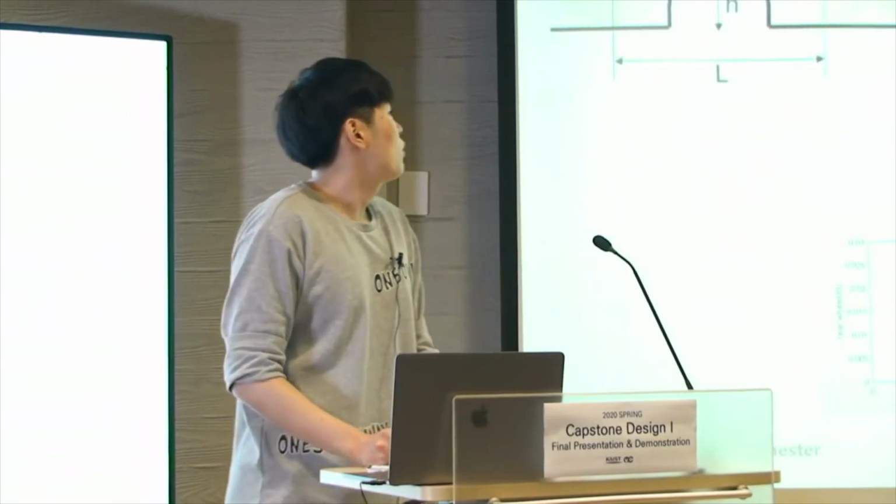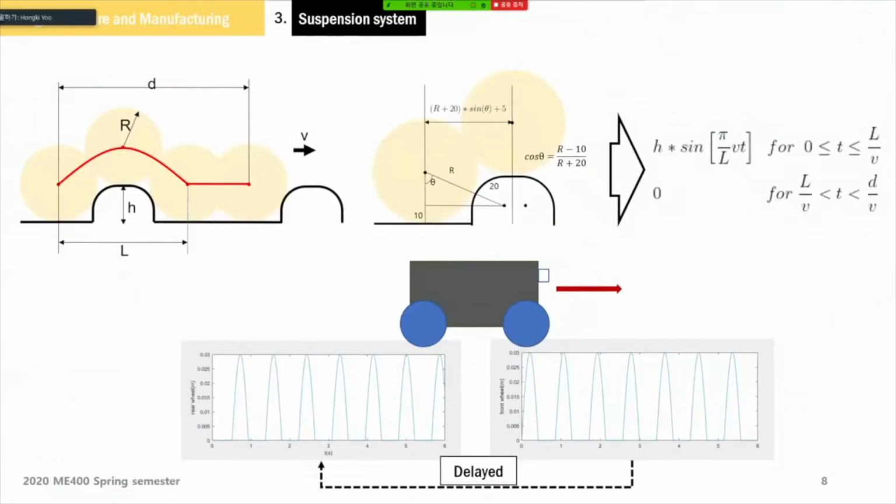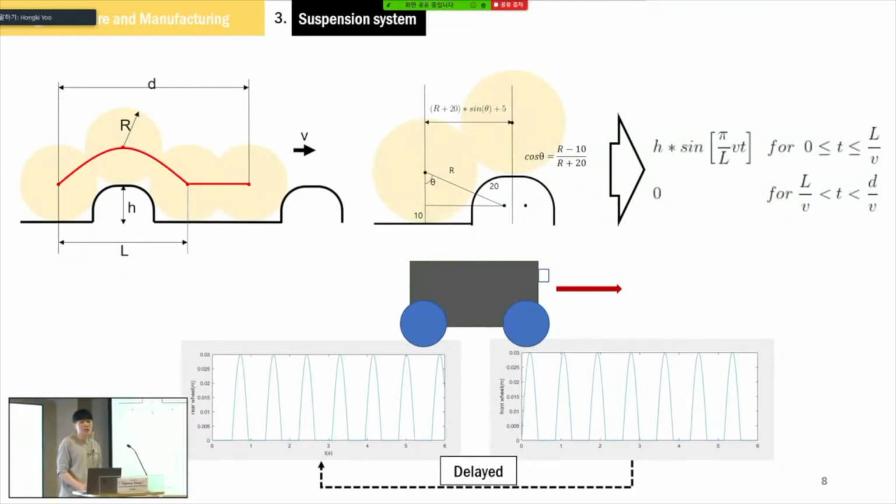Based on field motion, we modeled base excitation input signal for state space system. The signal is approximated to periodic half-sine signal. We consider factors such as velocity and field size and bumper distance. And rear field signal is delayed due to the distance between front field and rear field.